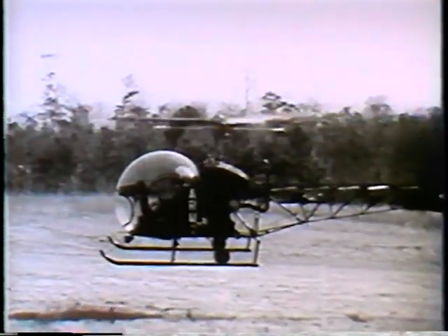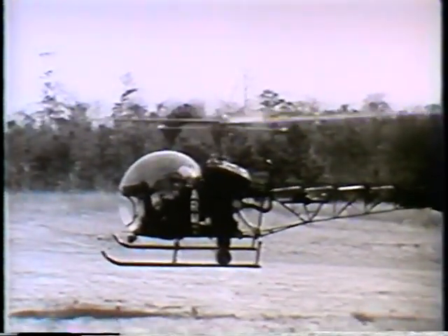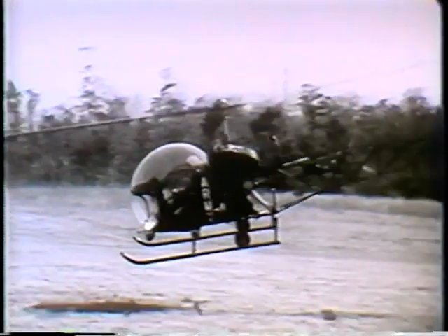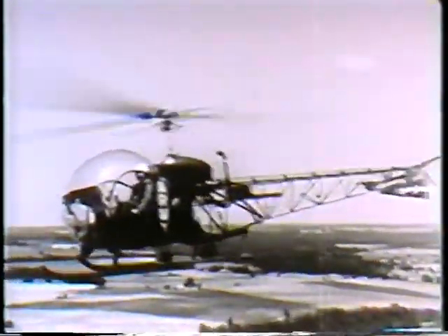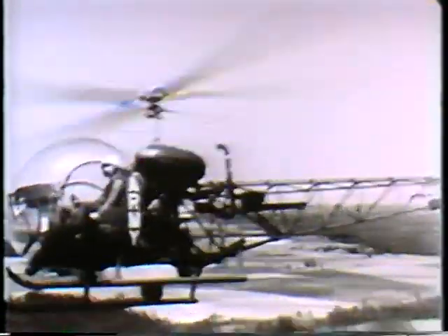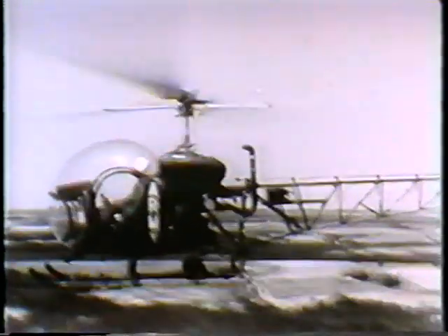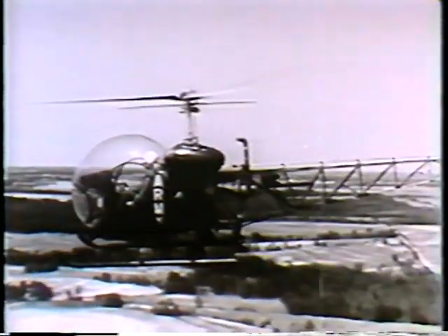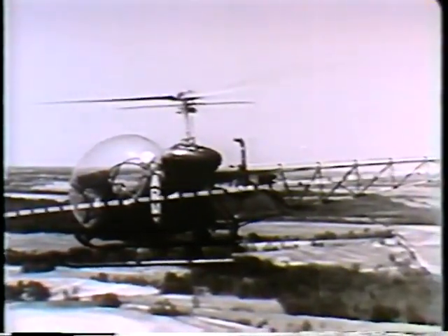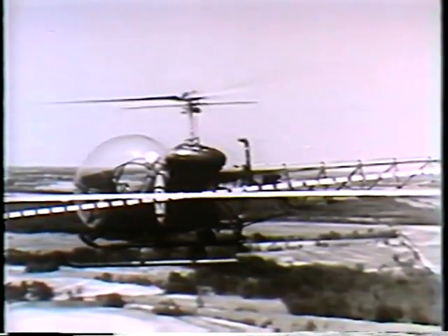When this happens in flight, the rotor disc is made to tilt, and the helicopter moves off in the direction in which the disc is tilted. This results in a change of attitude in the helicopter. The aircraft tilts in the same direction as the disc is tilted. Attitude is the angle of the entire aircraft relative to the horizon.